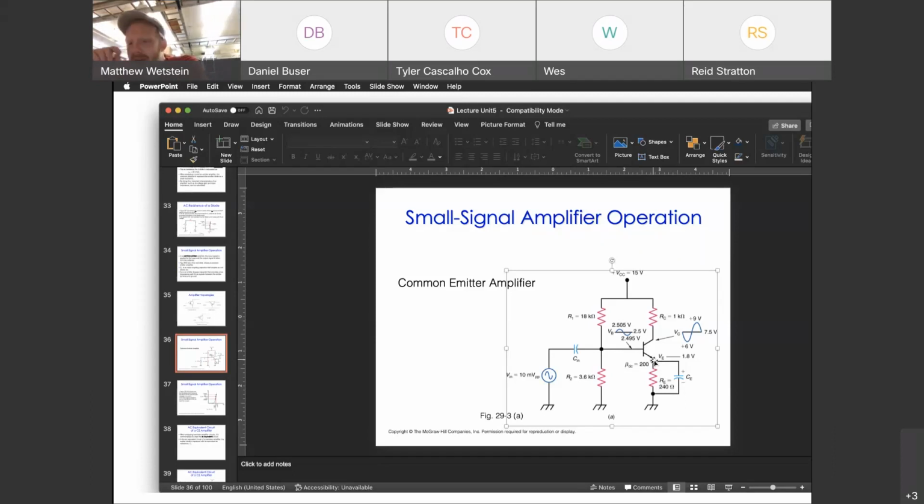Where do we pick off the output of this transistor amplifier if it's a common emitter, if the emitter is tied to common ground, AC tied? Correct, the collector. And similarly, if it's a common collector, the signal is taken from the emitter. And remember, a common collector has the second name, which makes it confusing, that it is an emitter follower.